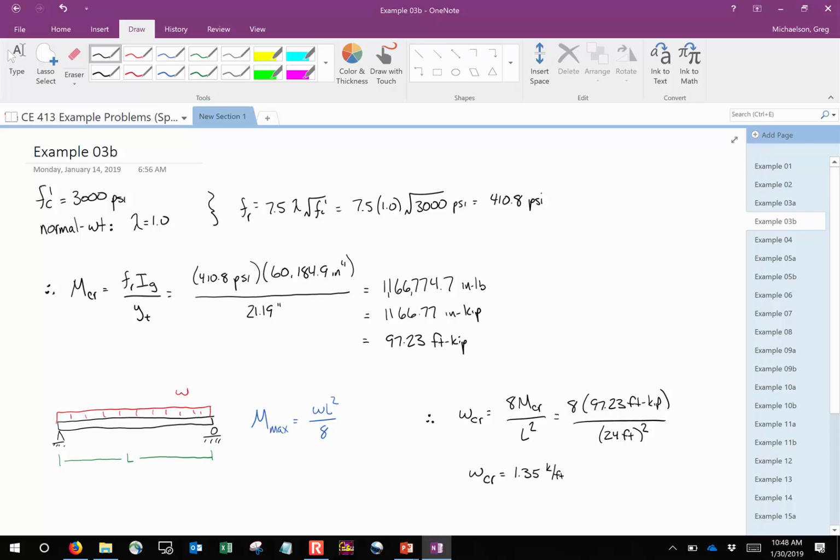Well, we can assume that the beam is reinforced, so we can assume a unit weight. You're on to something. We had this formula in our notes. How do you determine the self-weight of a beam? The specific weight times the area. Y'all remember that? It's in there, I promise. It's somewhere around slide 60 or so. But what I will do is this: I will say that this 1.35 kips per foot includes self-weight, and for now, we can go ahead and call that the answer.